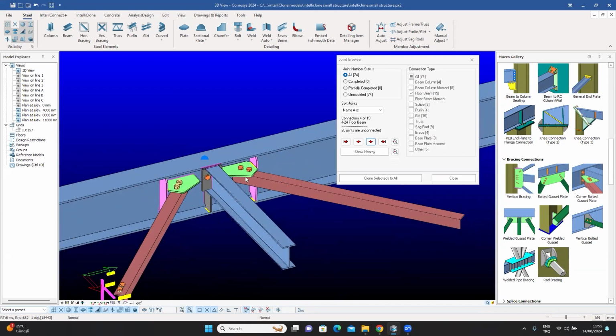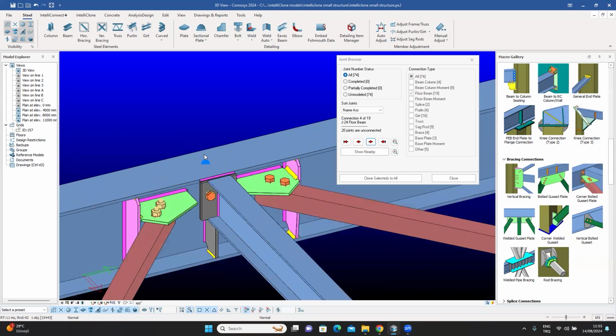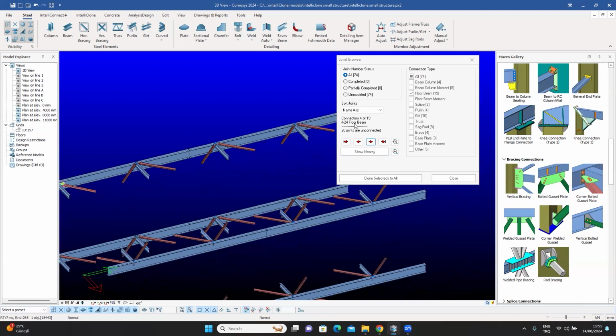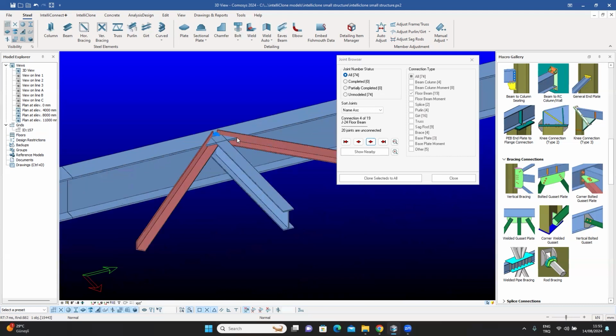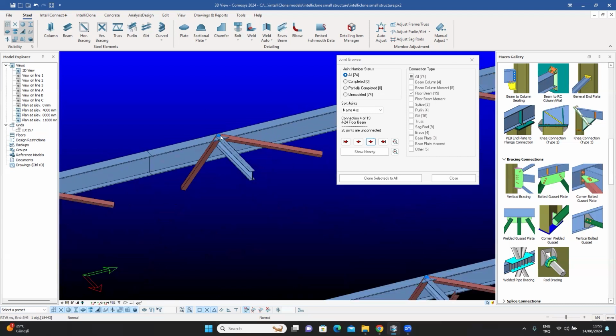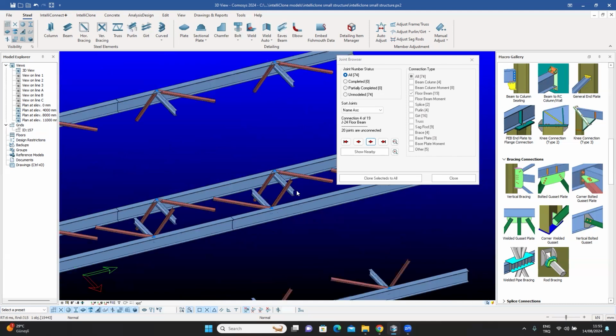I rotated the horizontal bracings. I moved them down. I shifted them to the left. I shifted them to the right. And I made some macros and connections. Now, what do I do? If you remember, the targets, the other 20 places where the same situation occurs, they have not been adjusted. They're still in their original configuration as they were. So there's a lot of work to be done over there.